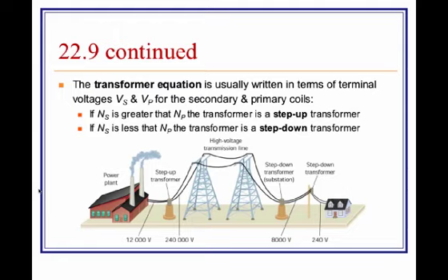The step-up transformer increases the voltage from the power source so that it can be transmitted over a longer distance with less power loss due to resistive heating and other things. And then at the other end, by your house, you need a step-down transformer, which translates that voltage to a lower voltage. It's a bigger step-down transformer. You'll see these outside of cities and towns, and then you have another step-down transformer right outside your house. Those are the boxes on the telephone poles, and they step it down to something that your house can use.